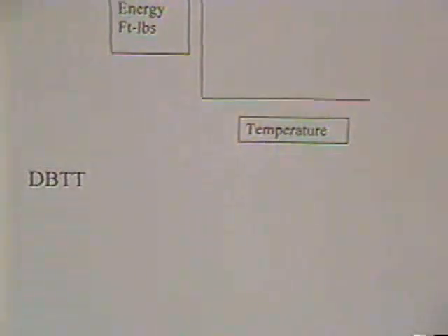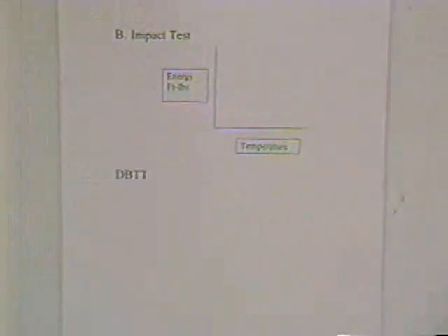Now, another mechanical property that is important is the measure of how a material behaves under impact load. The tensile test is a real good measure of the behavior of a material under a static load. The sinking of the Titanic is a nice example of materials that were strong enough and had sufficient ductility. They didn't know enough to evaluate them for their impact characteristics. And once it crushed into that iceberg, the material behaved in a brittle fashion, so a number of cracks opened, not the 300-foot gash that was first originally thought.